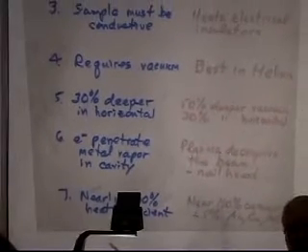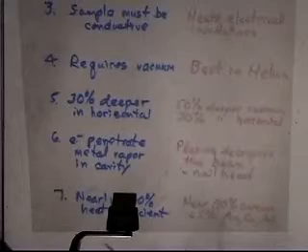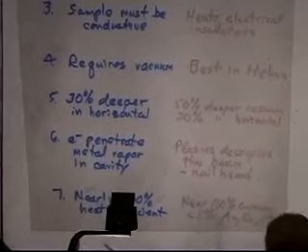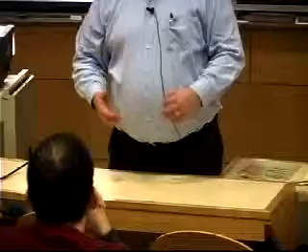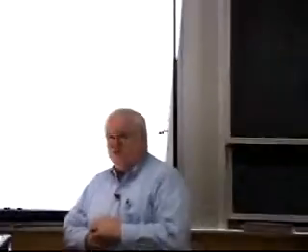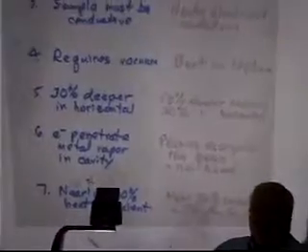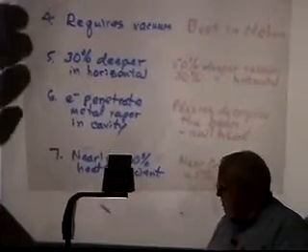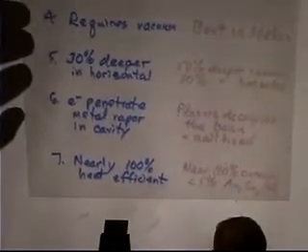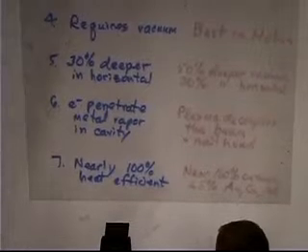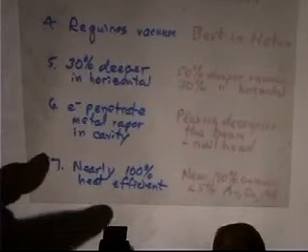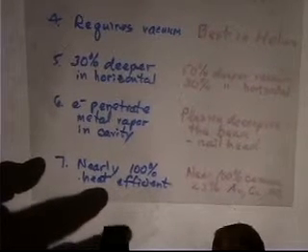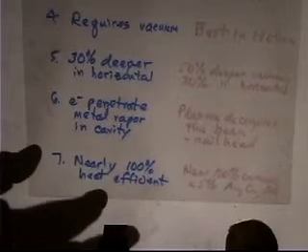And so you'd like to blow that metal vapor away, and typically, if I'm laser welding here, I will have a transverse flow of helium gas. And the reason I use helium is because it has the highest ionization potential. It's the most difficult inert gas to strip electrons from. And so if I'm in the United States and I can afford helium for my laser shielding, I blow my vapors away with helium gas to prevent formation of free electrons, which would absorb the incoming light.